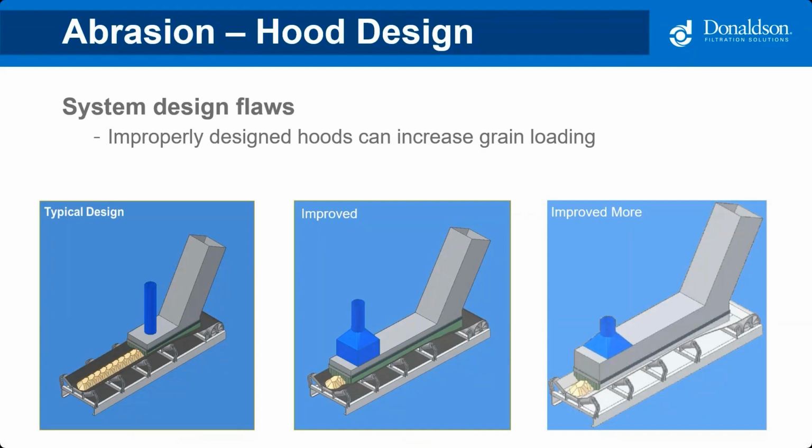Maybe you want to elongate that capture area a little bit to help the dust settle down onto the conveying belt. But more importantly, you're going to want to get that straight pipe out of there. And you're going to want to allow a little bit of a drop zone where all the heavy sand is actually going to stay on the conveying belt where it's supposed to be, and it's not going to get sucked in. So just a real simple change in your pickup points can make a lot of difference in the dust collector.